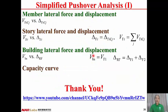Okay, in this lecture, in order to conduct pushover analysis, it has been simplified so that it can be manipulated by hand. There are three stages for simplified pushover analysis. The first one is member level. We have to find out the force relationship of those vertical members, such as columns. That's Vfi Cj versus delta Fi Cj.